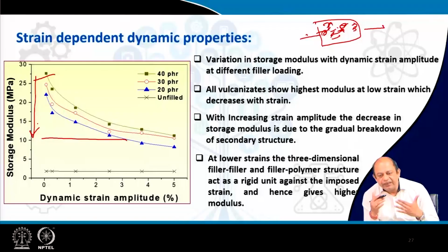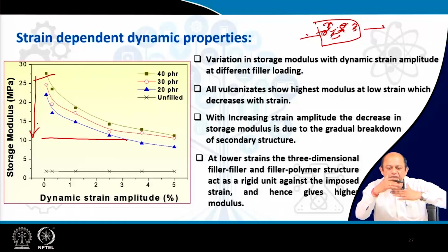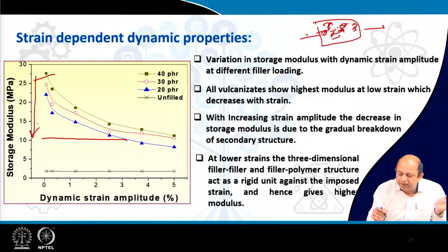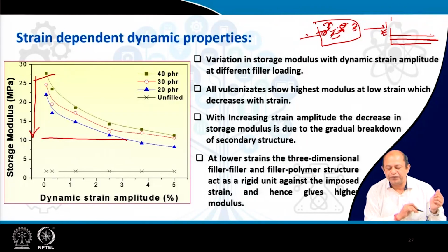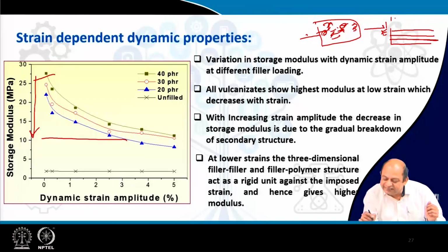In fact, if you look at the composite modulus, I can draw it here. Initially, the first part of the total strain is because of the rubber component. Then you put in filler, and there will be a hydrodynamic component. Then you have a rubber-filler interaction part. Those at a small amplitude will not break down. Then what is the aggregate part?